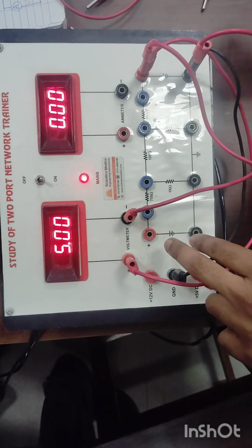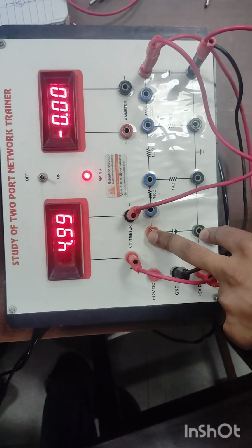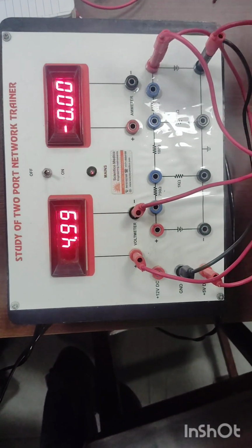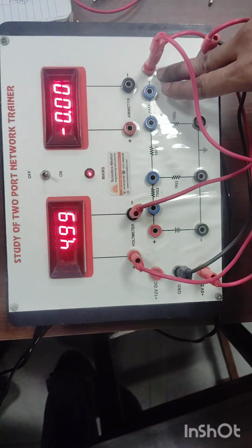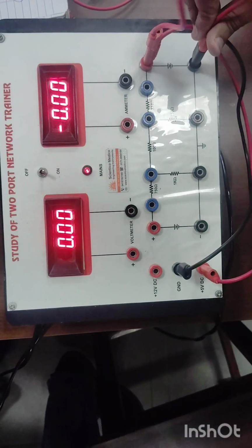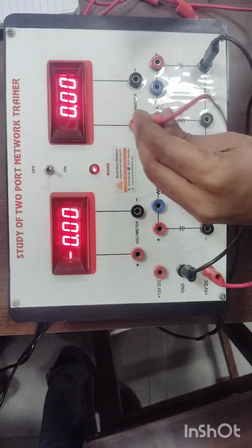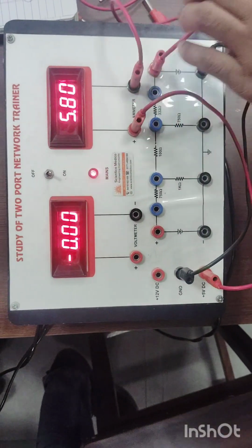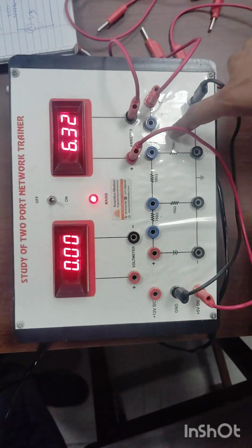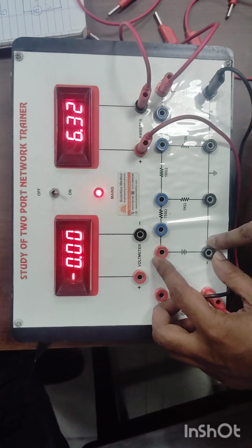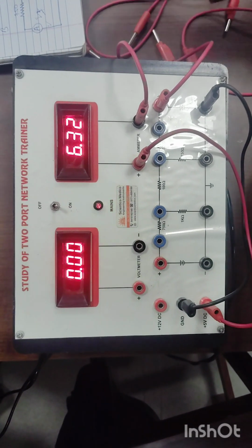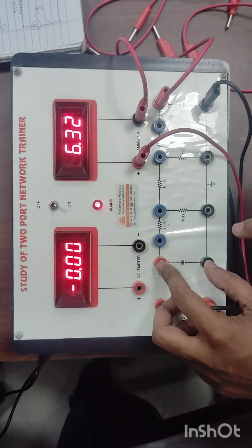In the third case we need to open the AB terminal at the starting side of the circuit, and we also need to measure the I2 current, which we collect from these two terminals. Here we need to connect the ammeter in series. So like this we connect the ammeter with the source. This is your I2, which we collect from this loop, and the AB terminal at the starting point has been opened. Done.